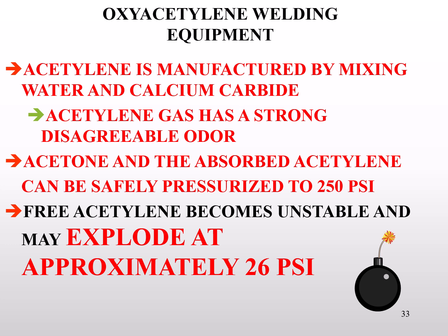Acetylene by itself becomes extremely unstable above roughly 15 psi, and it will explode without an ignition source at approximately 26 psi. So as you can see, if we're going to take acetylene gas and pressurize it to 250 psi, we have to stabilize it, and that's the purpose of the acetone. By absorbing it into that liquid, we can then pressurize the gas to a high enough level to make it useful for us with welding equipment.